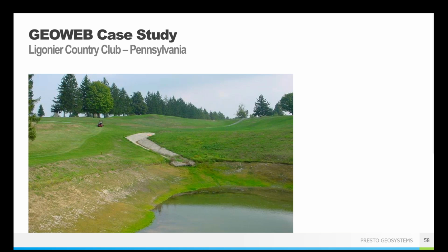But it's really nice because you can have significantly reduced concrete depth when using the GeoWeb system. Also allows you to go around corners, curves, dips, hills, that sort of thing, contours to the landscape a lot better. So in this case, it's a chunk of concrete in the middle of your golf club, but it does look as natural as you're going to make concrete look. So it's a little nicer aesthetically and is a more economical solution than reinforced concrete.